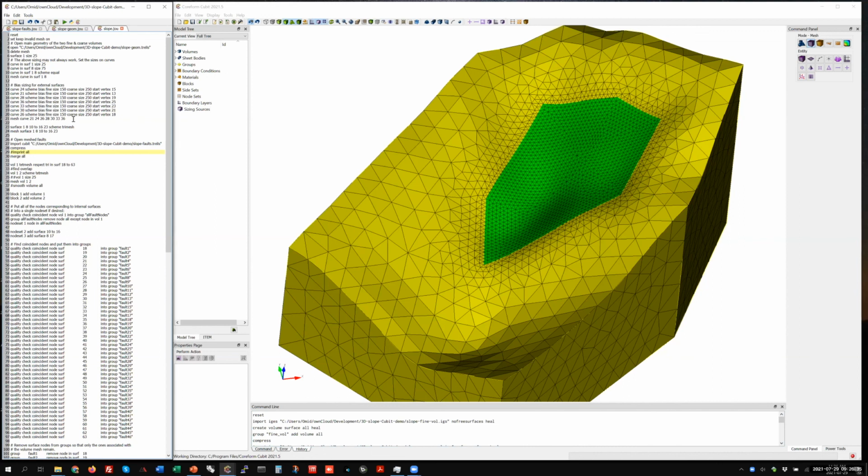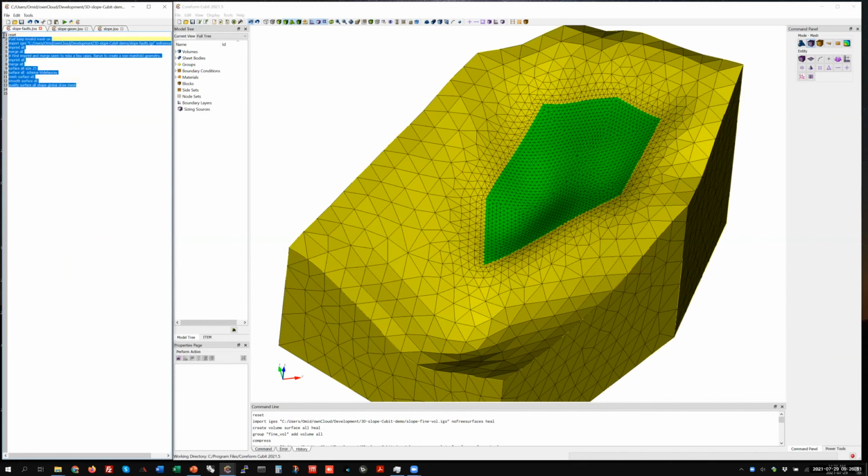And with that, you could really do a lot of things very quickly. It's very similar to recording a macro. My workflow is that I generally start clicking here and there. Then I start to record these into a journal file, and then I play that journal file. That way, if I have to do things iteratively a couple of times, I don't have to click 100 times and change, because every time you have to go through different menus and select different stuff.